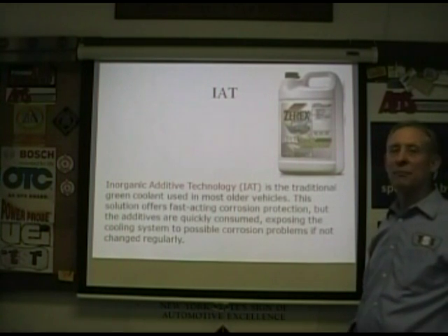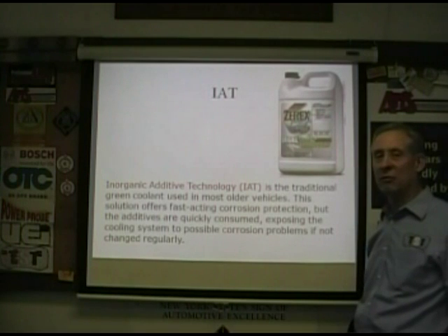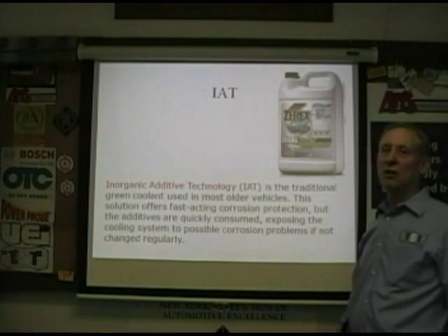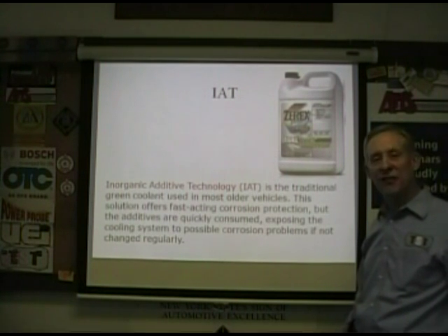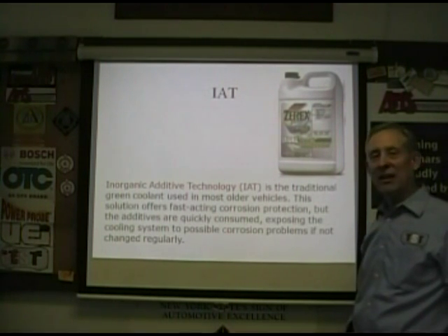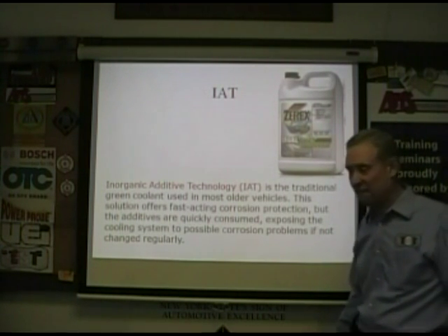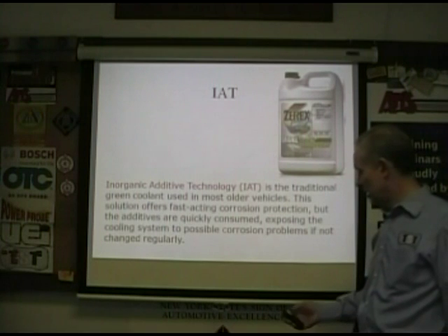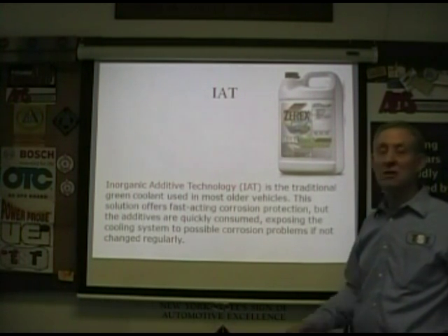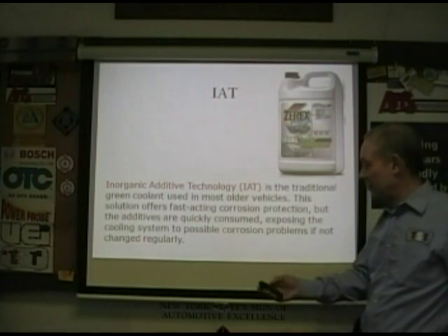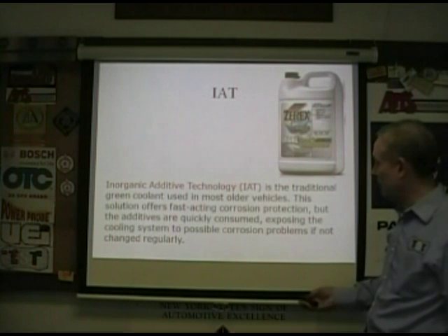And I was doing BMW exclusively at that point. We had unusual failures in BMW after a few years of those, where we had radiators that looked flawless. No broken fins, no plugged anything, and yet the coolant leaving the radiator was virtually the same temperature as the coolant getting into the radiator. There was no heat exchange going on. They came up with their own coolant. I started using their coolant with distilled water, and the radiators lasted virtually forever until they started raising pressures and temperatures and the plastic housings blew apart.